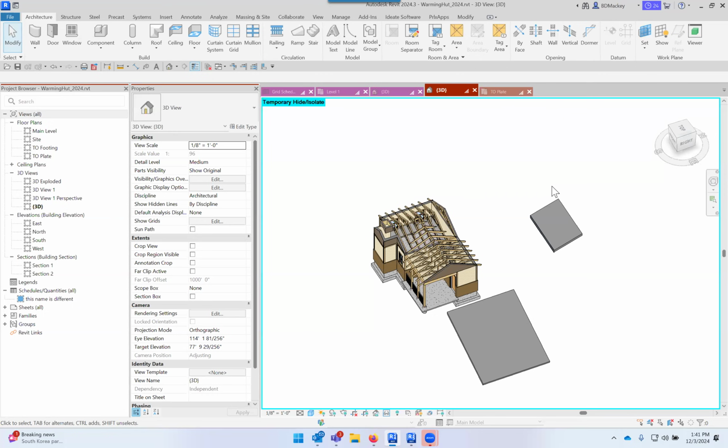And I've also seen the fact that, and I haven't done it lately, but it used to be when you did domes, you would get two semicircles rather than one whole half sphere, right? You'd get a quarter, you'd get a lemon wedge, not half of the lemon. So when you would start to rotate it to the other side, the adaptive component element could start rotating and flipping and doing bizarre stuff. So yeah, that's just a royal pain. Honest truth, I try to, like I said, draw a reference plane, a grid line, something that you could use the align command with in a section, assuming that family has a strong or named reference plane to align to.